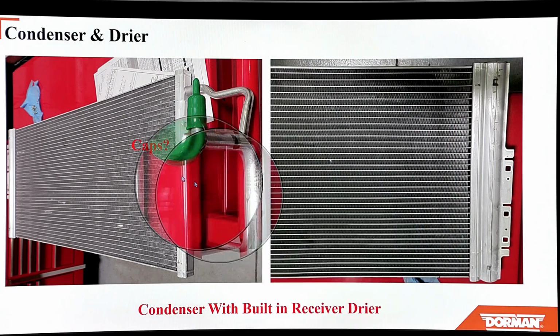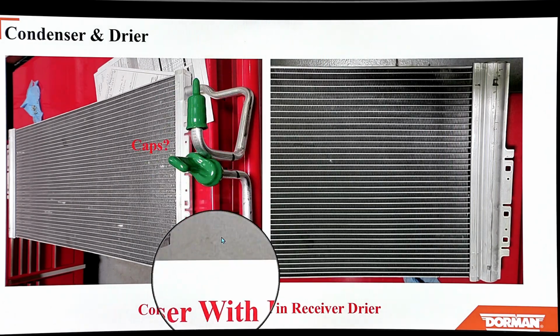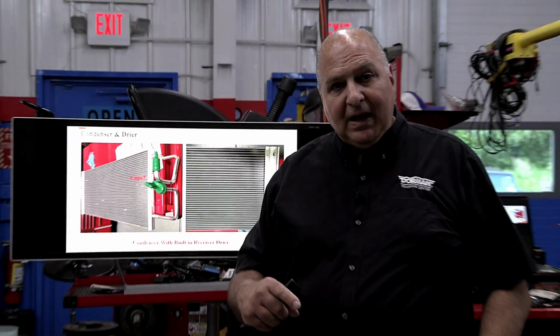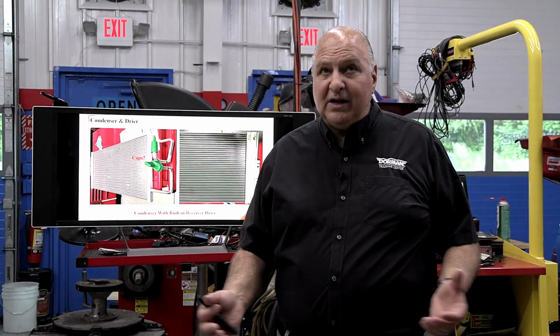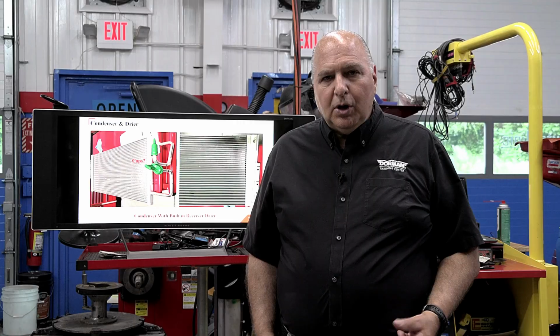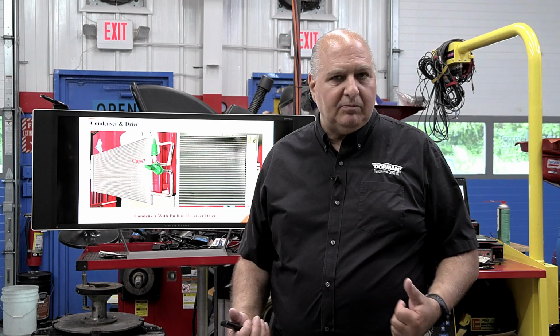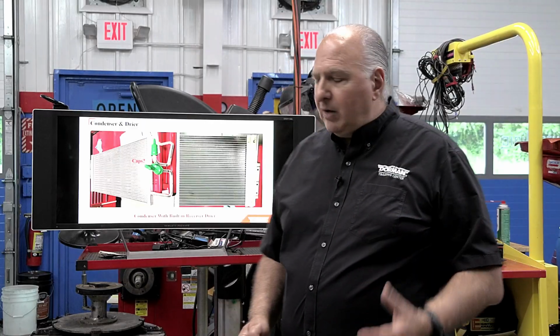Now, how about these caps? Do not remove caps until you remove the old component. And let's say you're going to lunch, right? It's our lunchtime here. We're going to put either those caps that we saved from one of them, or we're going to take Gorilla duct tape and seal everything up. Why? We don't want moisture getting in the system, okay? Because the moisture causes hydrofluoric acid. We don't want anything to get ruined in the system.